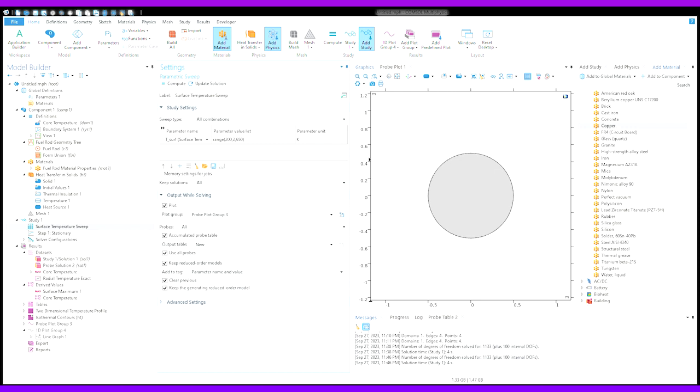So first off, you'll recall from the last problem we wanted to find the hottest surface temperature that was allowable while also keeping the core from 650. So we found that out to be 616 Kelvin. So I'm just going to choose to plot the radial temperature profile at 616 Kelvin as the surface temperature.